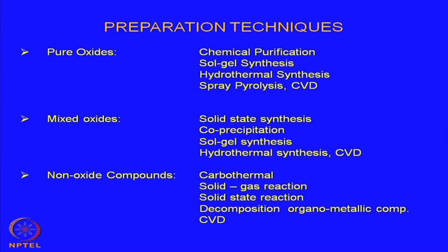in an inert atmosphere, so that the carbon does not get oxidized in presence of oxygen. So, oxygen should not be allowed when the reaction is going on. If you are talking about nitrides or even carbides, carbon can be taken in the form of solid carbon or gaseous, maybe carbon monoxide or some hydrocarbons. Hydrocarbons can be taken as a source of carbon, and then it can be allowed to react with some metals, so that the carbides can be formed.